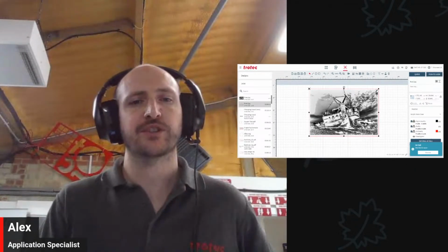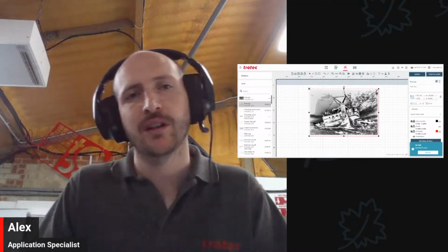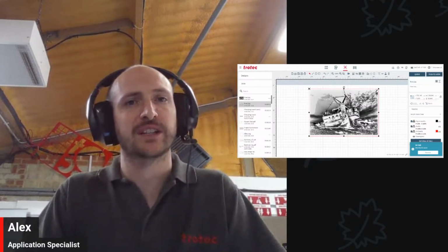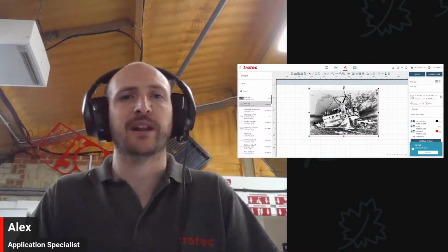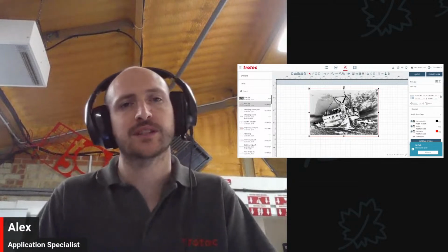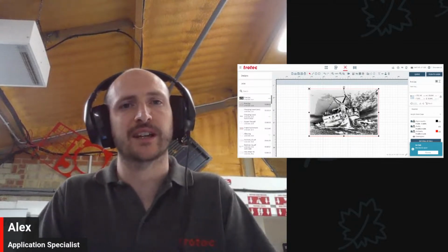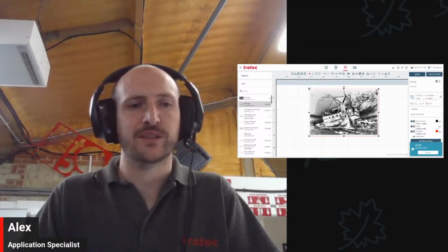By that I mean, especially on something like clear acrylic, you'll find you can very easily scratch it, especially if you're looking at edge lit applications. It's something you have to carefully balance. So you need to use a really soft cloth, even something like lens cleaning cloths could be useful, and then an actual dedicated acrylic cleaner is something that's good to use.